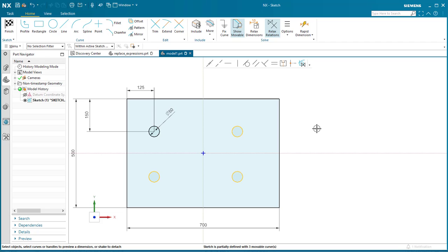Now we wish to add dimensions between these two circles. So if I click on the outer circle, it's going to get the shortest distance between the two. So that's going to be the 332 there. Once you click it, it'll activate it. And let's put in 350 and then click OK, and now we get the dimension between those two circles. Now between these two circles we want to do the center, so we select the circle, the center, and then the center of the other circle, and then add the 210 dimension.